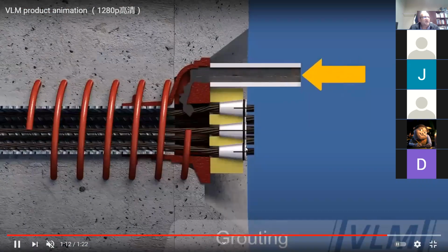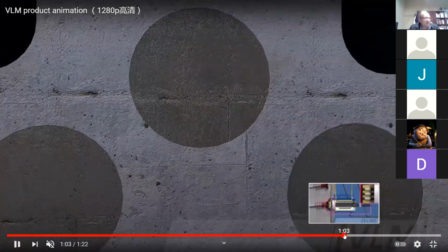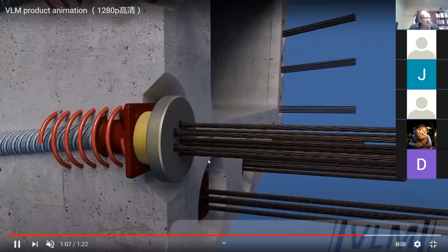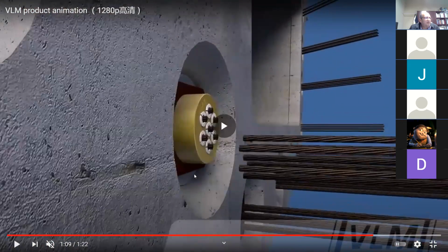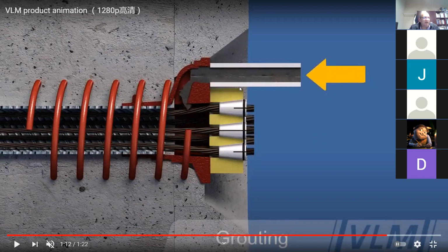Now you have pre-stress. You can also grout this, because look at this. Before you do this grout, there is no contact or bond. You don't have here any bond between the cables and the duct. In some cases, they leave it without grout, but this is not advisable because of the corrosion. You'd like to fill it in with grout. So first they clean it with air. You want to be sure that everything is very clean, and then they start to pump the grout in.